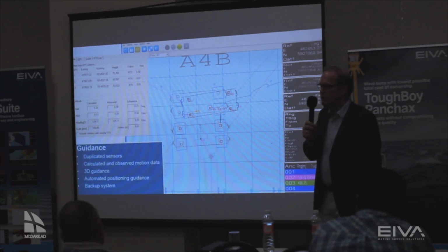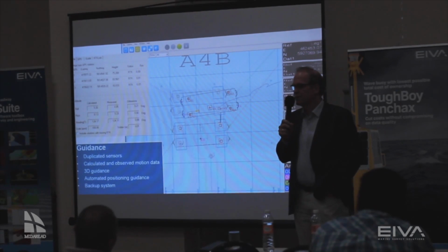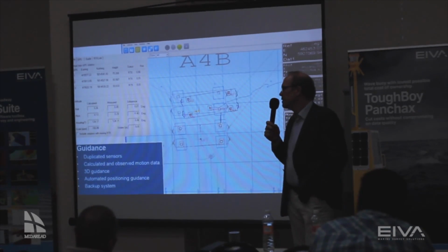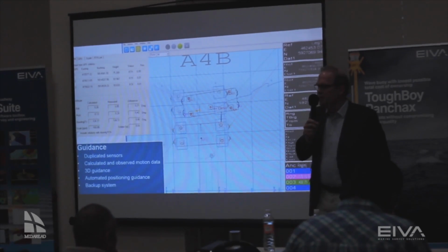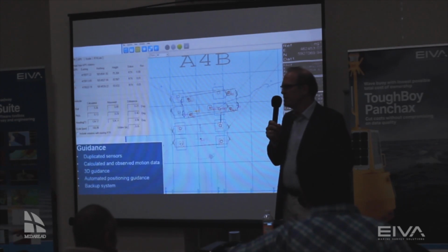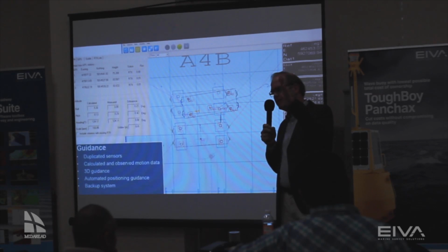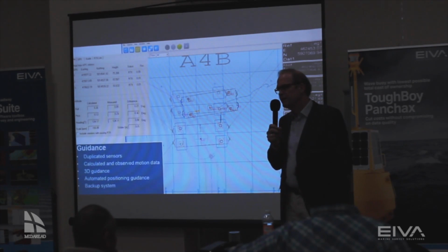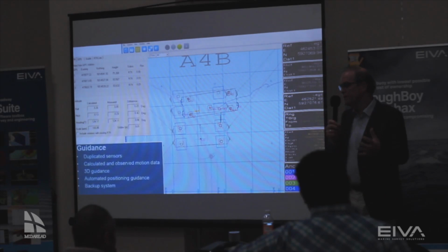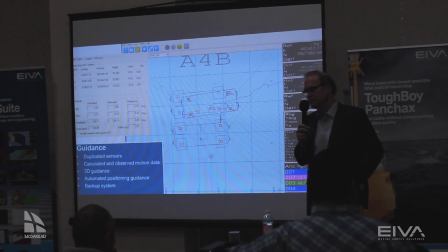They have a known net of reference stations over the world, covering the whole coastlines. And then these reference stations and the positions are calculated and sent to a satellite, and then you can apply to the satellite. You have to pay a monthly or a daily fee, and then you get these corrections directly on your vessel.